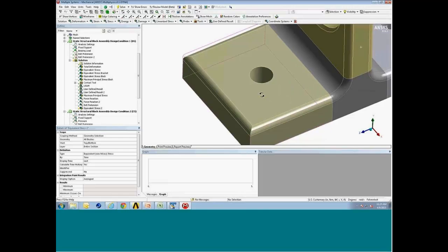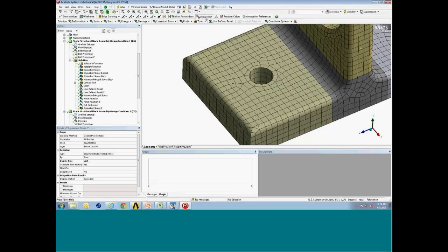To do this, once we've highlighted the area we want to focus in, we switch over to Show Mesh. This shows the mesh on the model, but then allows us to switch over to selecting mesh to scope this to this results quantity. So once we select the mesh, we can then pick our node selection method, either picking them singularly, a box select for surface available nodes, or a box volume and lasso volume to select certain nodes throughout the volume.